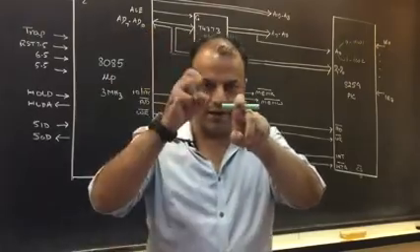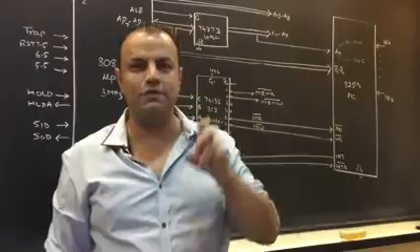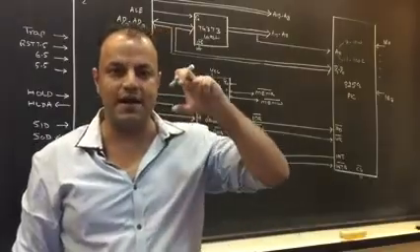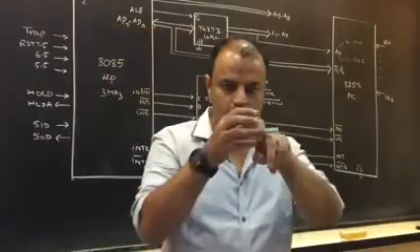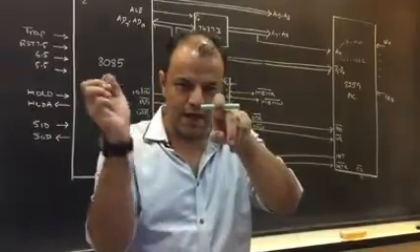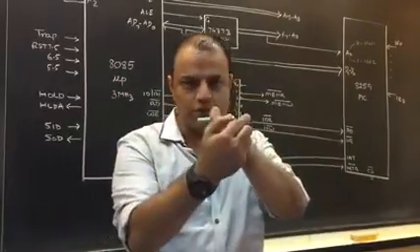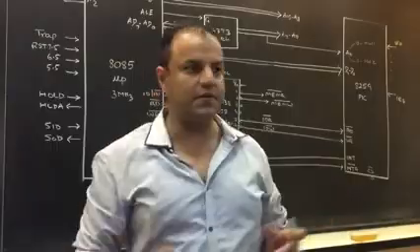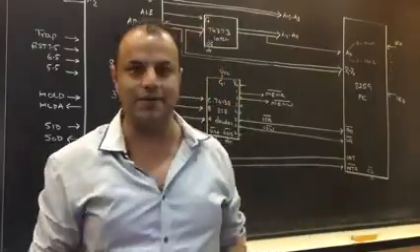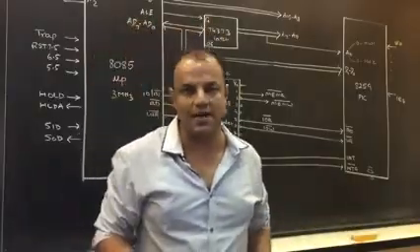What does a latch do? It captures the value. A latch is a set of flip-flops. A flip-flop can hold 1 bit. An 8-bit latch will hold an 8-bit value like 25. So use an 8-bit latch. Now what happens? I send 25, 25 comes out from here. So did the latch amplify the signal? No. Did it increase the driving capacity? No. People write these stupid things because they don't know what a latch does.